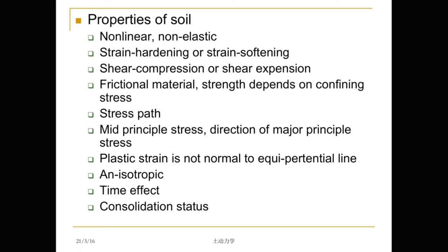We know that if you apply the shear first, then apply the normal stress, it will cause larger deformation. But if you first apply the normal force, and then in the next stage apply the shear stress, then the deformation is not so much. That's the effect of stress path.